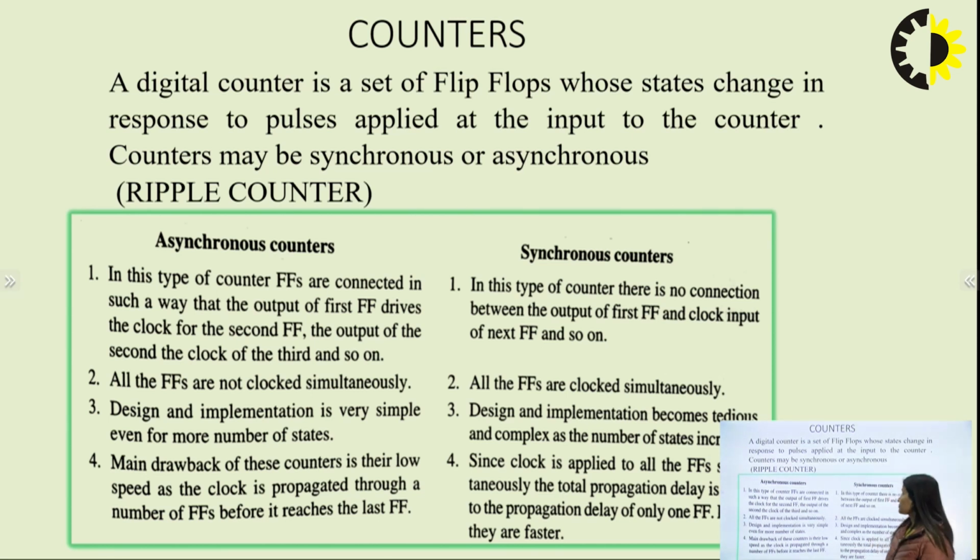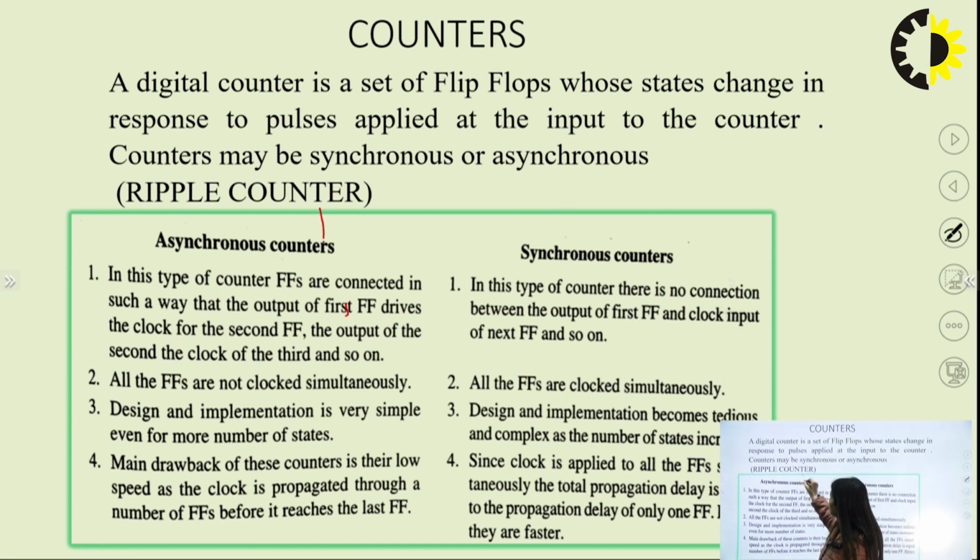That means if I want to make an asynchronous counter, let's say I am using two flip-flops. This is a T flip-flop, this is the output. Again, this is a T flip-flop, this is the output. The output of the first flip-flop is connected to the clock of the next.